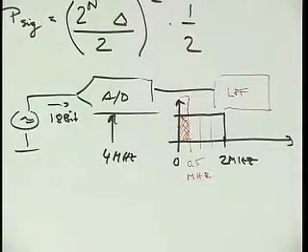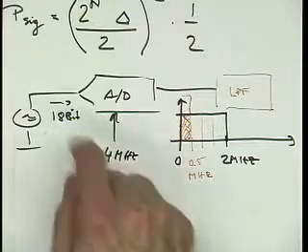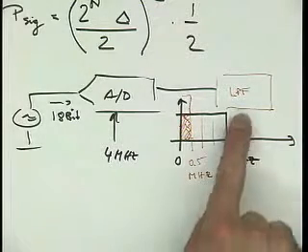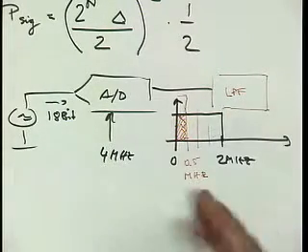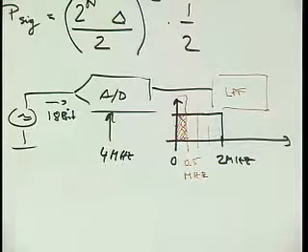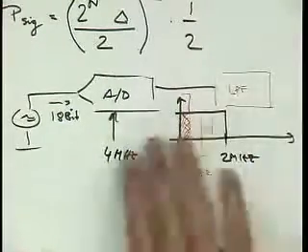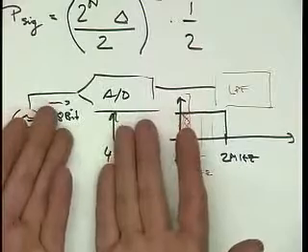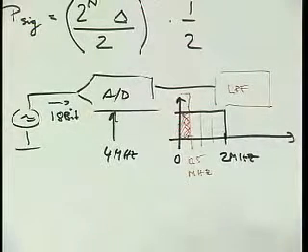We haven't really done anything. But sometimes what this does is, instead of building here an incredibly huge capacitor, we use a smaller capacitor, run our circuit real fast, then we use a digital processor, called a low-pass filter here, that sort of has noise gain, to use RF parlance, processing gain, that removes all of this extra bandwidth that we had here by running this fast for no real reason except for this noise, because our signal had only 500 kilohertz bandwidth, say, and then we pocket the extra bits in terms of signal to thermal noise performance. So that's one way to get around it, but that's about the only one I know.